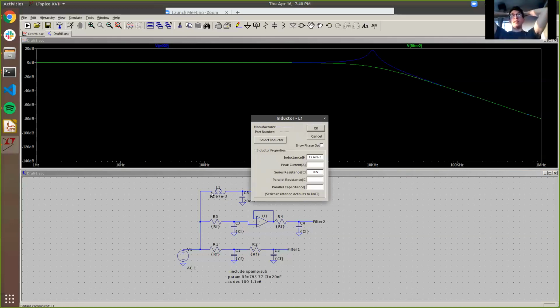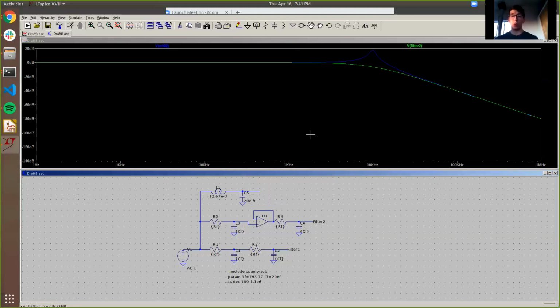To hundreds of milliohms. 1,000 milliohms is a single ohm, and you probably don't want even that. That's still quite a bit. So that's why 100 ohms would be absurd, literally illogical for the amount of ESR you're going to see in an inductor. I hope you never buy it, at least. Sure. Yeah, great question. Other questions?